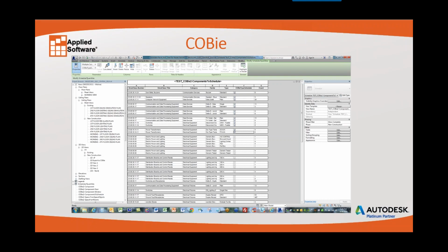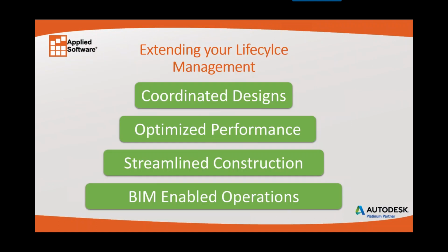For those of you not familiar with COBie, COBie is what gives you the ability to tag all these different thousands of pieces of information of parts within your building with a distinct OmniClass number. It's like a social security number that each one of us would have, but imagine your building having social security numbers on every little thing, and it's automatic. The only thing is now any of those tags or IDs just need to have a QR code associated with them. Now, how can this be done? This can be done through Revit, through BIM, Building Ops, and A360.